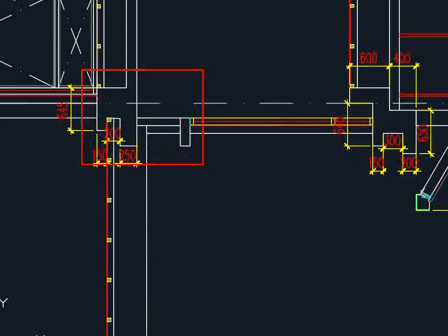Same goes for this section. Now you have a white beam here, and you have 2 additional fins here, and you have a fin which is at the offset distance above the top level of the beam. You have to find a way to have this in one piece along the beam span. These are the things that you have to take into consideration regarding the architectural features.